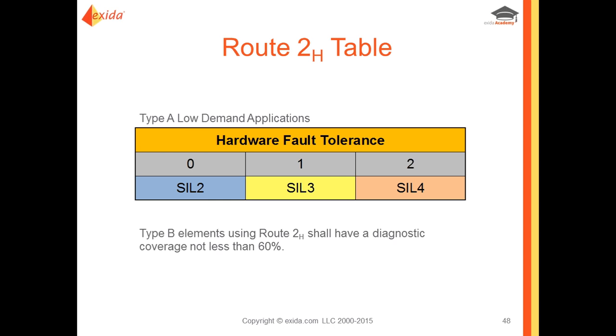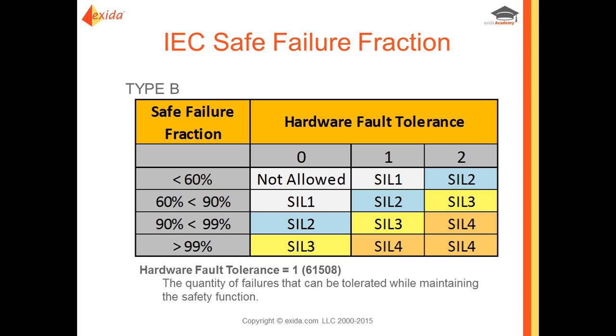So just for an example, solenoids and pressure switches are simple devices that IEC 61508 defines as type A devices. Therefore, looking at the chart, a safe failure fraction of 0% with no redundancy, so hardware fault tolerance equal to 0, meets SIL 1. Unfortunately, say you were looking for SIL 2, so something must be improved, and we're going to look through that for an example. Oh, I should have pulled this chart up.